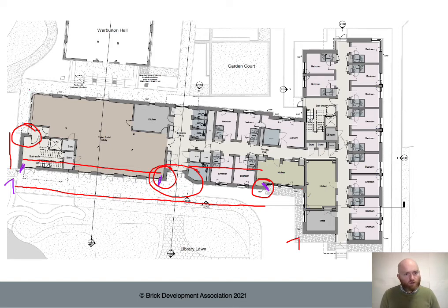Moving within this corner, and then we have a very long section of brickwork here, and it looks like we probably have a short return there. So I think what I want to do is debond that short return from the longer panels of brickwork, and then actually we're back to 12 meters from this corner. It looks like there's a couple of rainwater pipes in there, so actually maybe what we'll do is put a movement joint in there behind that rainwater pipe.